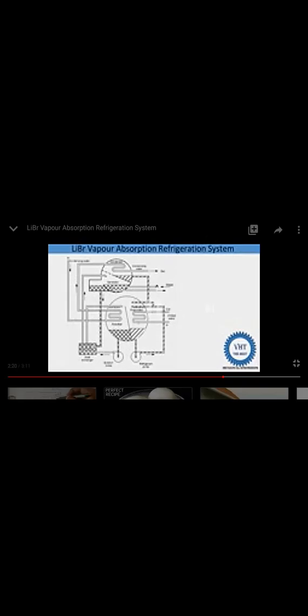And this lower pressure cell, evaporators and absorbers. So water is refrigerant, lithium bromide is absorbers. Now another component is this refrigerating pump, this is the solution pump, this is the heat exchangers. So these are the main components: absorbers, evaporator, generator, condensers, refrigerating pump and solution pump, and one heat exchangers.